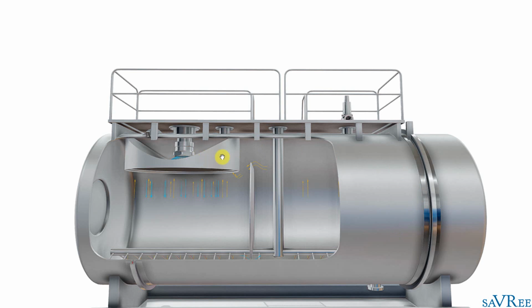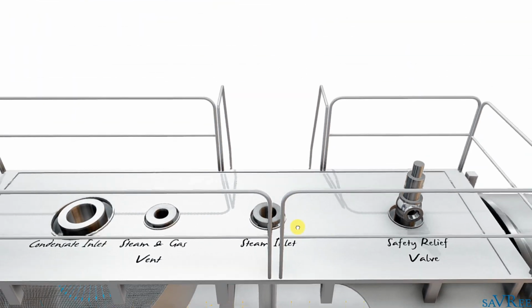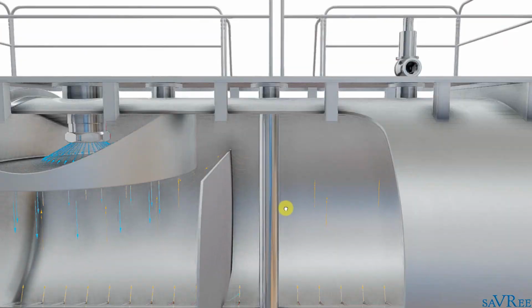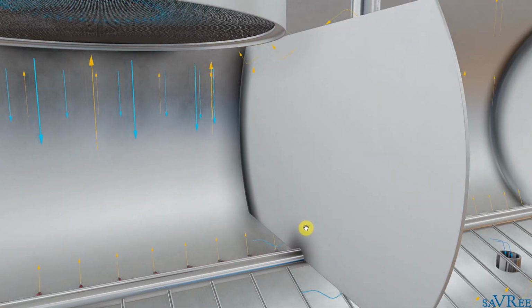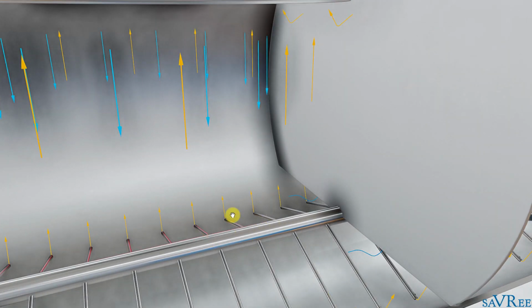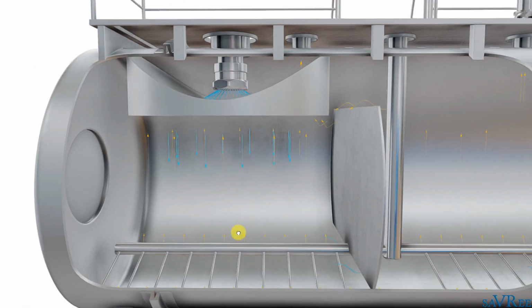We deaerate to reduce the number of dissolved gases in the boiler feedwater and condensate. You can see that steam enters the deaerator through this pipe here. It comes down the pipe and is then discharged through a sparge pipe or sparger pipe. Steam comes out here. We can see our yellow arrows. It will bubble up through our boiler feedwater.